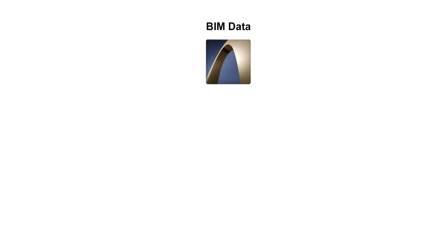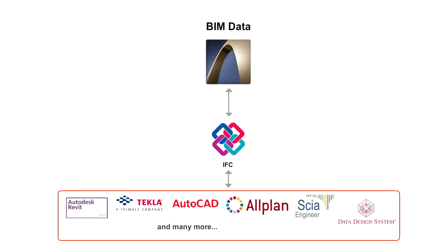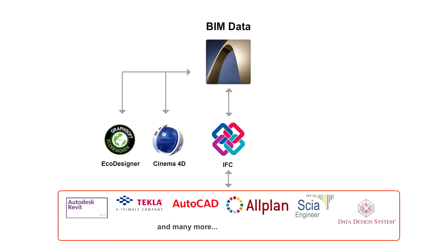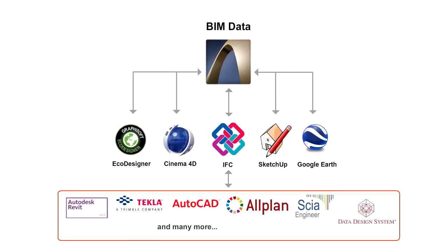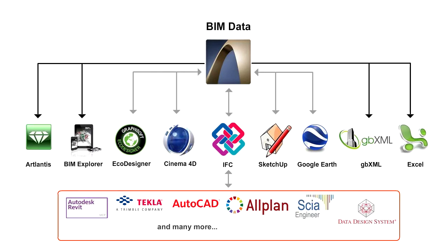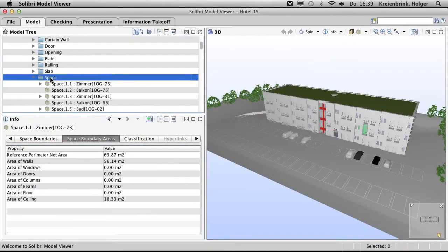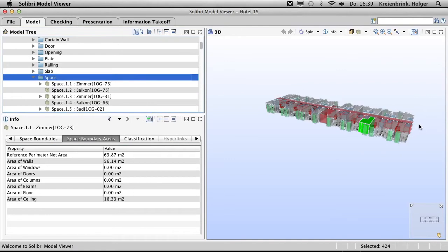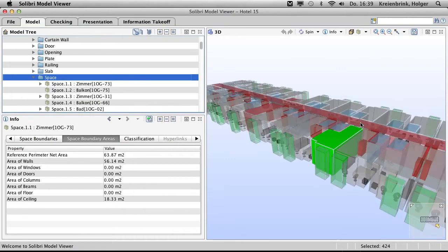In addition to 2D data, you can output the 3D model as well, for rendering purposes or to exchange project data with other disciplines. For 3D model exchange, the IFC format is used. With IFC, the complete building, including the intelligent structures, is shared, so that a consultant who imports the project receives real zones, walls, windows, doors, slabs, and beams.